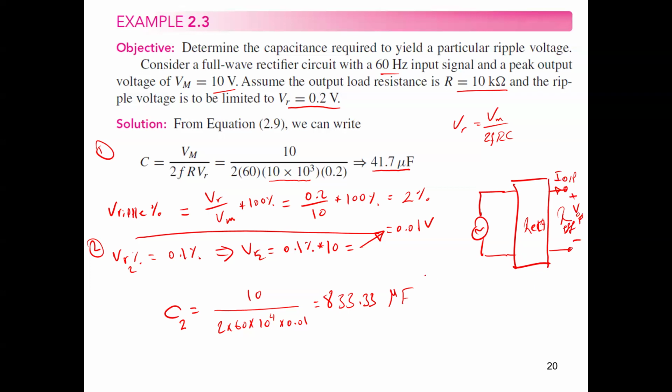So this is also one important thing you need to understand, because you may not have your load resistance given in reality. But in numerical problems, as you can see, it's very easy to give it as given data in the problem. In reality, you may need to calculate or estimate the load resistance in order to calculate the capacitance needed for your rectifier.